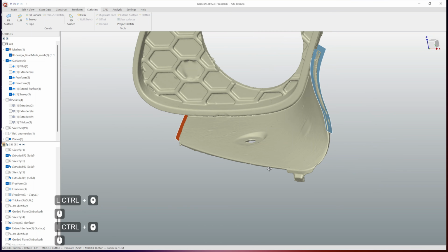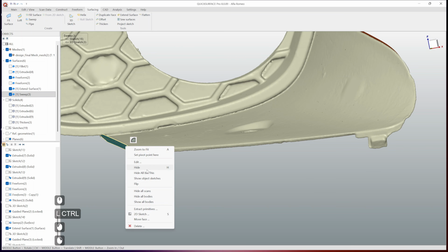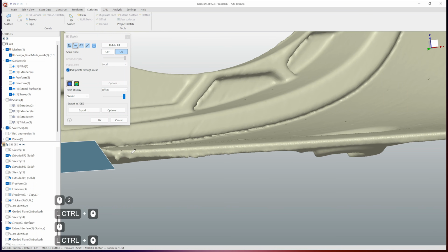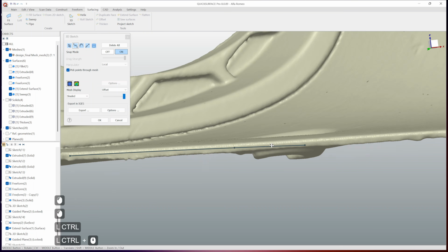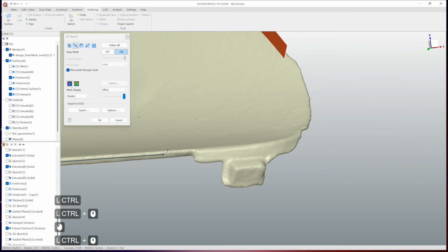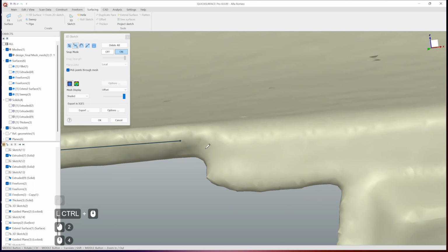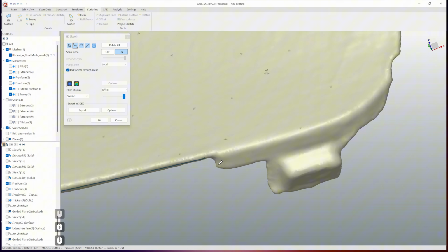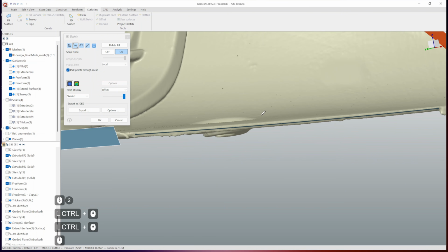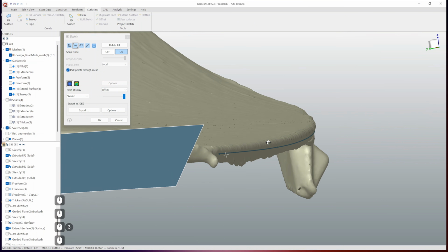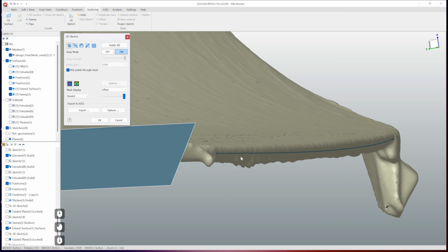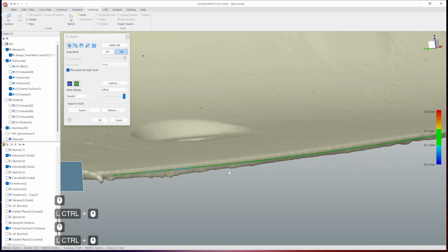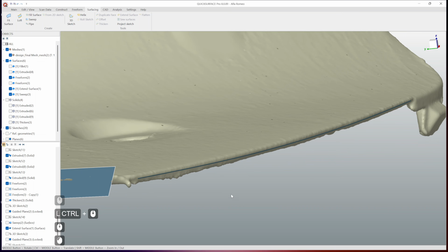So now at this point, I can proceed to the front edge here. So I'm just going to create another sweep with a 3D curve. Say something like this. Not to go over this corner. This corner I'll have to recreate a different way. So currently I'm focusing on, say, main surfaces. And deviation control shows it's good enough. So let's accept this one.